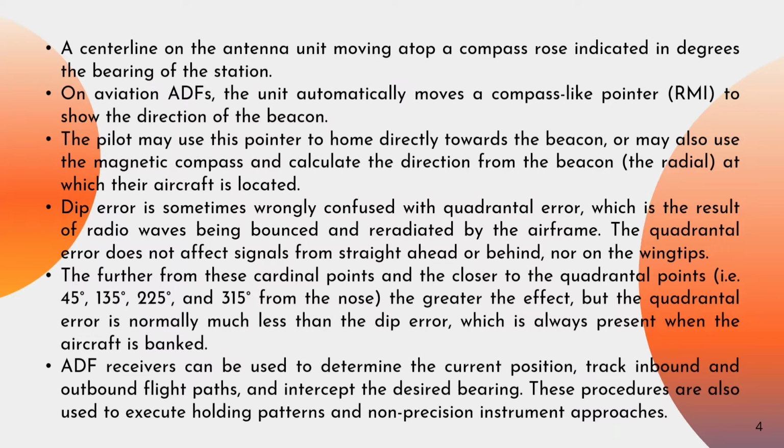The ADF receivers can be used to determine the current position, track inbound and outbound flight paths, and intercept the desired bearing. These procedures are also used to execute holding patterns and non-precision instrument approaches.